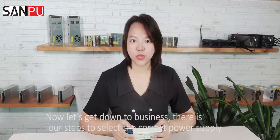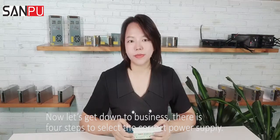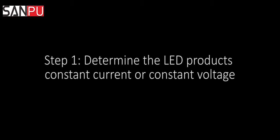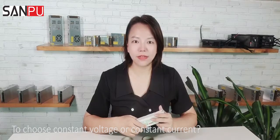Now let's get down to business. There are 4 steps to select the correct power supply. Step 1. Determine whether the LED product is constant current or constant voltage. To choose constant current or constant voltage, generally it depends on our product.